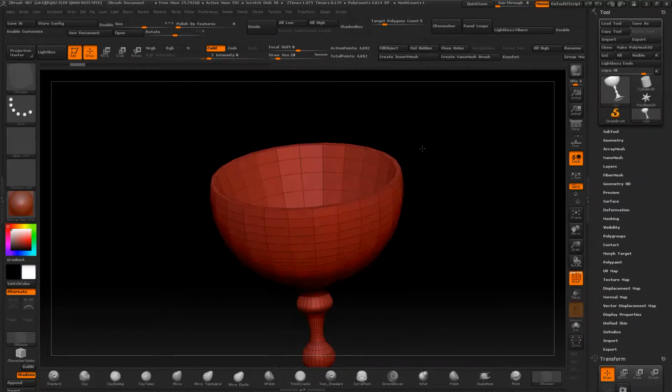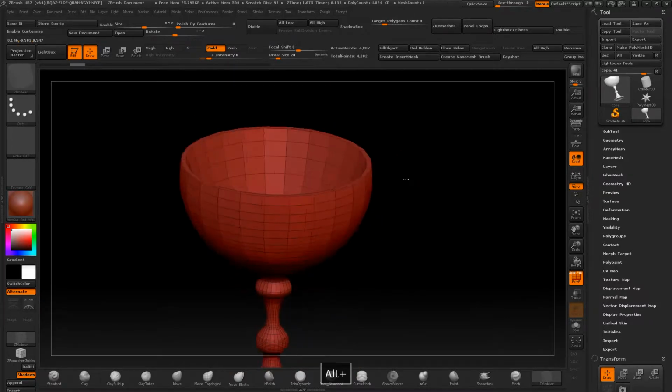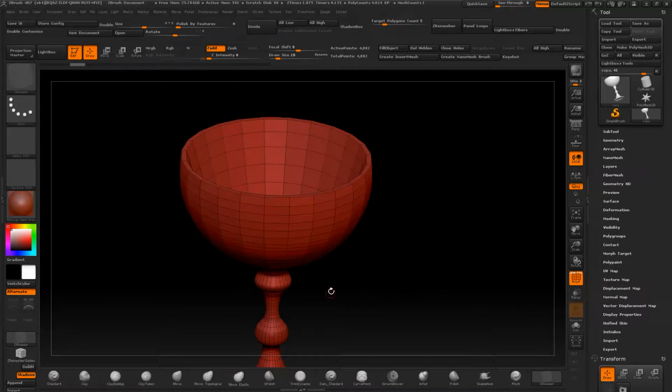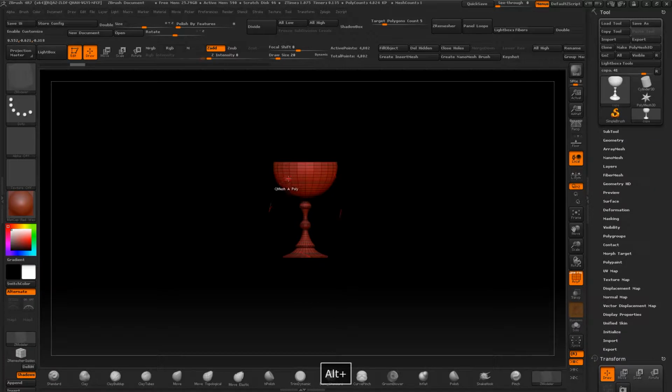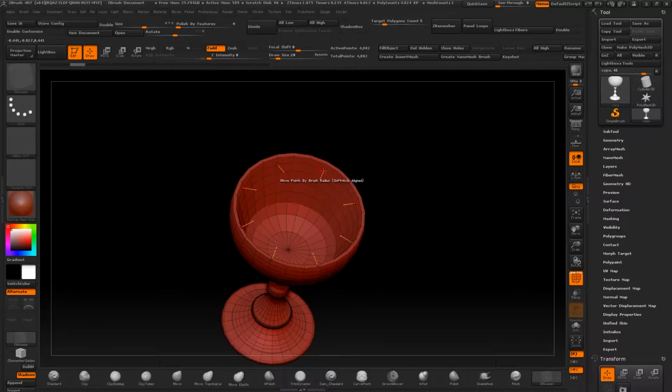And why did I just count like this? Well, I needed the practice. No, it's because obviously in ZBrush, you can make a symmetry, but you obviously make a circular symmetry, okay? We're going to hit the X key, and you can see I have this on, all right? So if you mark this other box, we make the circular symmetry, okay? In this case, see? So here we would need to put in the number of symmetries that we want and the plane that we're looking for. This one isn't good. This one isn't good. We need more symmetries.